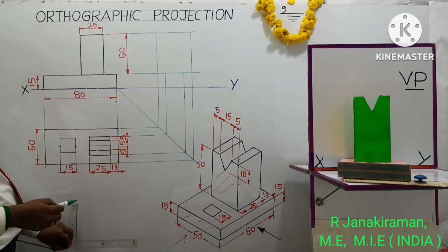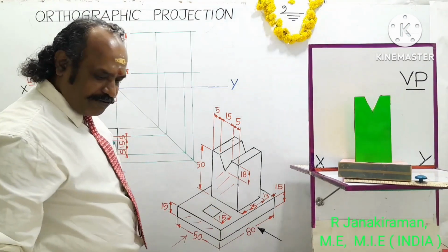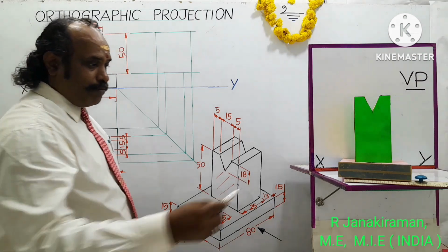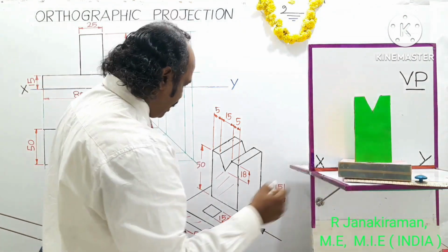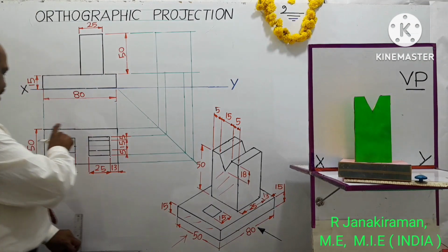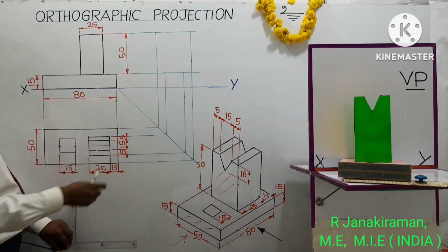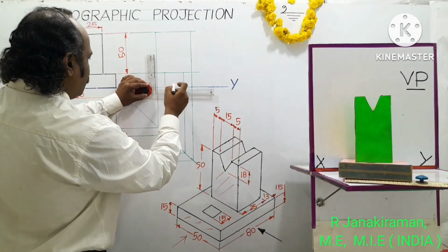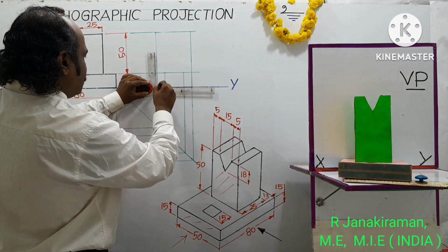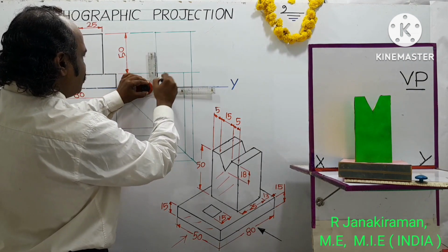Understand? So the portion visible in the side view will be the base part. Having 50 mm is the side given. This 50 turns like this upward, so that this will be the base part. Draw HB pencil lines, object line.